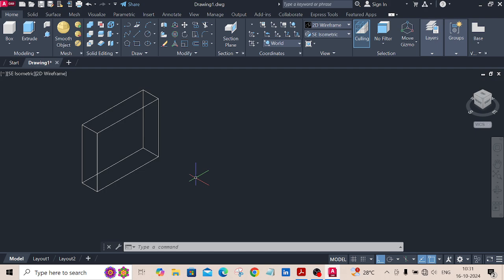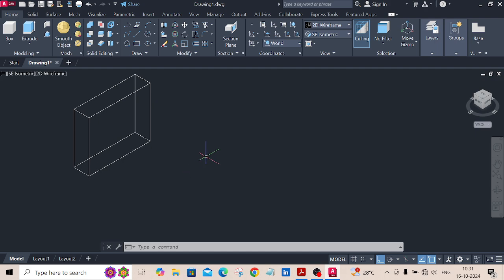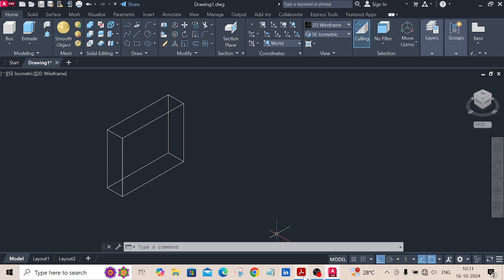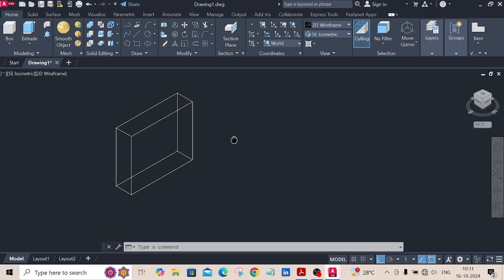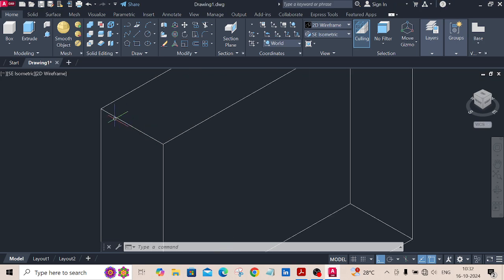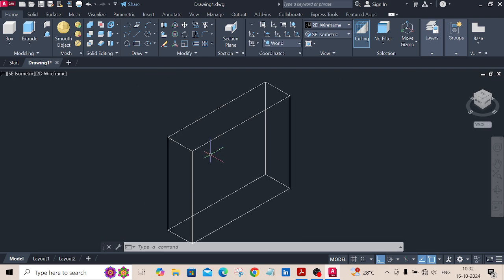Now the second primitive, this primitive having one more option, this inclined chamfer 100 cross 100. Okay, chamfer. So let us do that. One by one we will complete the command. This edge should be chamfered. Okay, this dimension is the first distance, this is the second distance. Both are the same, 100 cross 100.